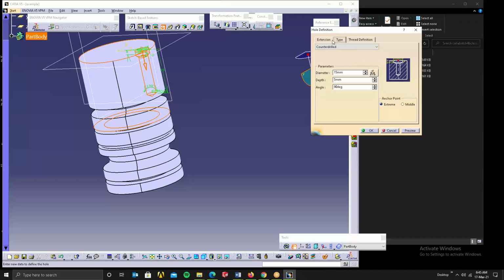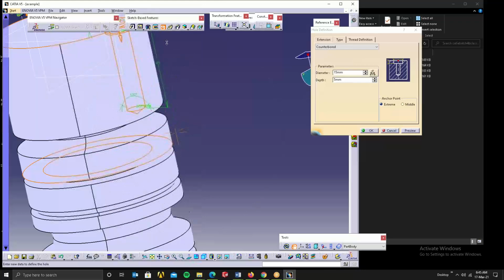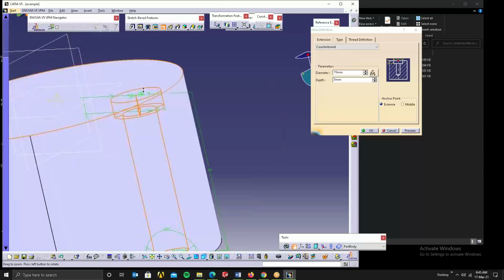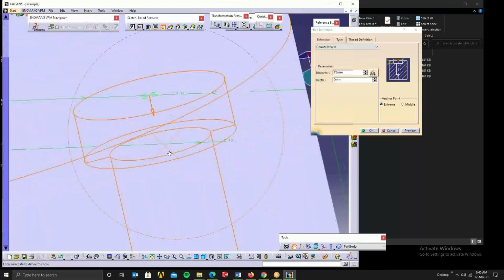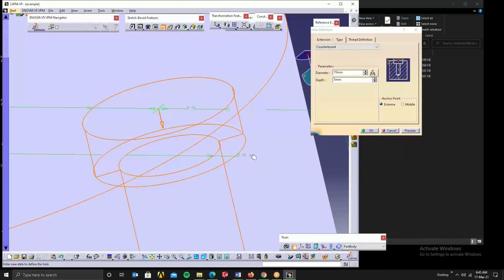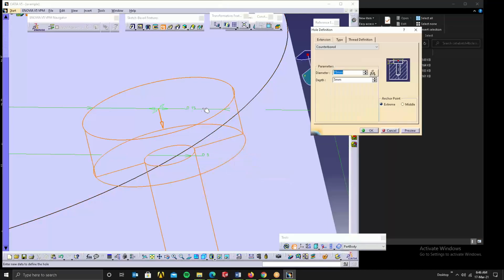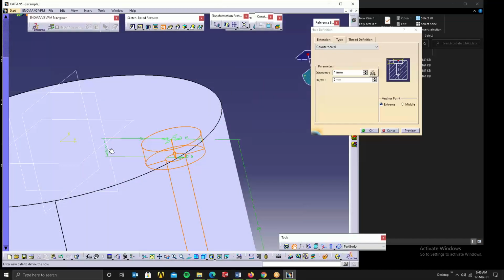Now one more thing I'll tell you, simply for simplification: don't use the dimensions here. Make sure you change the dimensions from within the sketch. Go here, whatever you want, 120 degrees is here. Just zoom in and change it from here. It's much more convenient, and you won't make any mistakes. See, here it is 10 diameter. I can make it 5, and this thing is 15. Let it be 15. And here, this thing is how much?